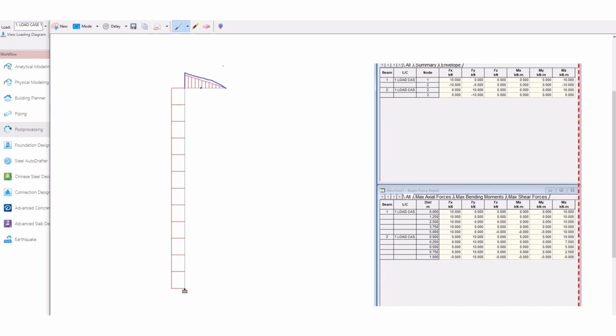That's why the bending moment is going from this point. It is force into distance, whatever this distance is. That distance is, I think, 1 meter, and we applied 10 kilonewton. So if you see, the moment is 10 kilonewton meter, right? This is 10 and the distance is 1 meter. So here the moment is 10 kilonewton meter. For this member this is the only moment there, and this axial force will come. This moment is the same throughout, because this is the force and this is the distance. For this member the force is parallel, so whatever the moment at this point, it will be a constant moment.